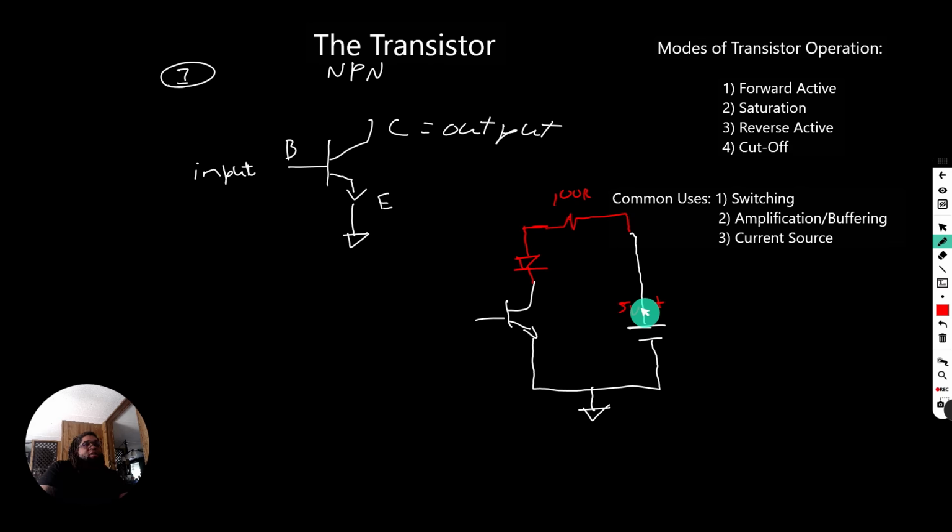The LED doesn't come on basically because the cathode end of the LED, which is denoted by that red line, is connected to the collector of our transistor. So to figure out what the LED is doing, we have to figure out the condition of the transistor. If the power is going through the resistor and the LED to the collector, that means the transistor has positive voltage, right?